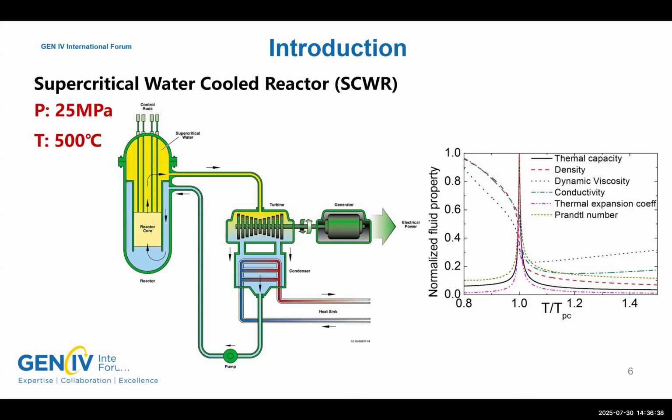You also see that the conductivity, Prandtl number, and the thermal expansion coefficient all go through a very sharp decrease or increase, or some very big change. I think this brings challenges for the design and the operation of the SCWR. So this is the key point. The high pressure and high temperature are among the most important thermal-hydraulic characteristics of SCWR.